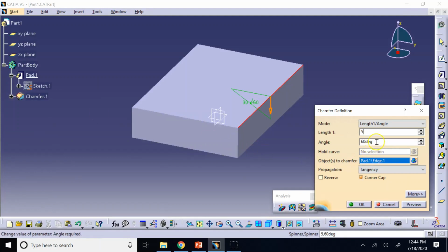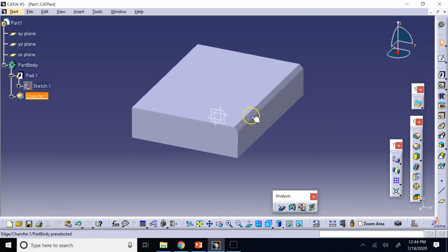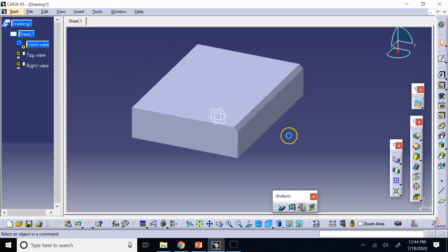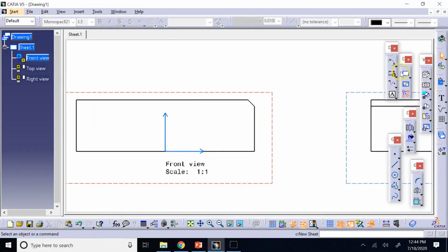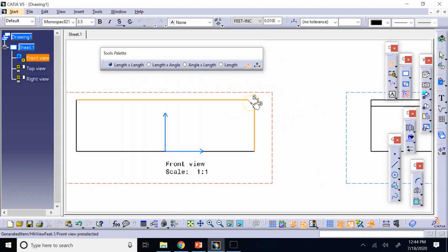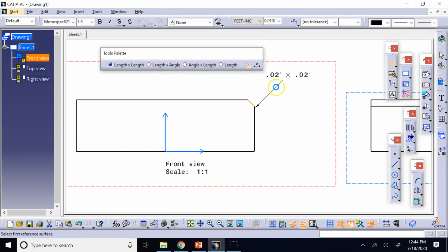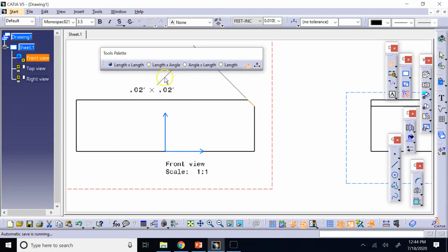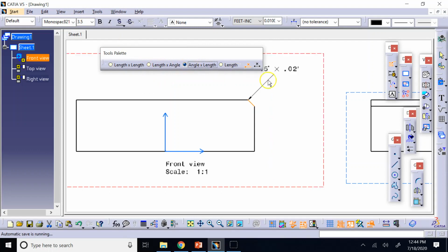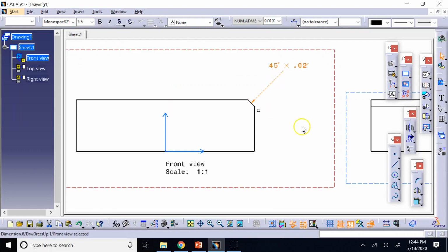that is meant to just get rid of a sharp edge like that, then you're not going to do this. Look, you're not going to do that. Instead, use the Chamfer tool, which is this one itself, and all you need is to click on the edge. And then here, the tool palette again allows you, do you want angle, or do you want what? Length angle. And you click on it, and that's it. Done. Okay?